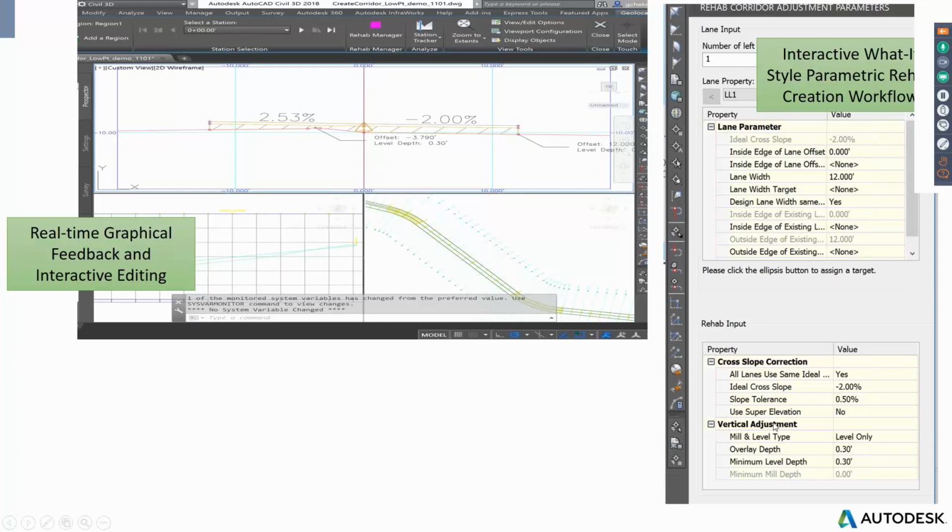And these settings that I'm doing on the right side are going to create a subassembly behind the scenes, or use one of the stock subassemblies that I have, and set it to these needs, its properties. It is going to build me an assembly and apply that assembly to build this corridor. So in the past, if you are creating a corridor object, you are starting with an assembly, attach sub-assemblies that you want.